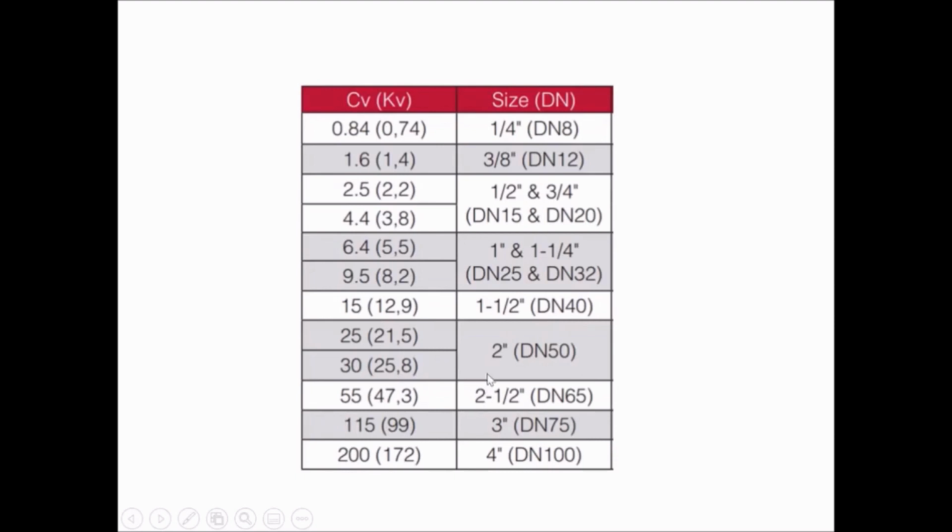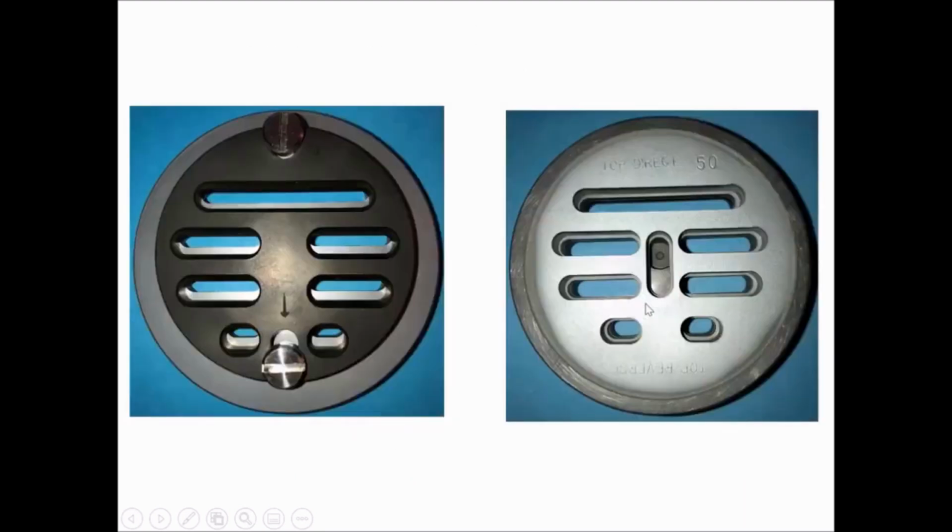When we have a 2-inch product, a control valve or pressure regulator, you can always go smaller in CV, right? You can always get a smaller orifice in the larger line sizes. If you have a 2-inch valve, you can't go up, right? There's only so much orifice available in that pipe diameter, in that line size. So if you're looking at this, you can always go down in CV. You can never go up past how much flow you're getting.